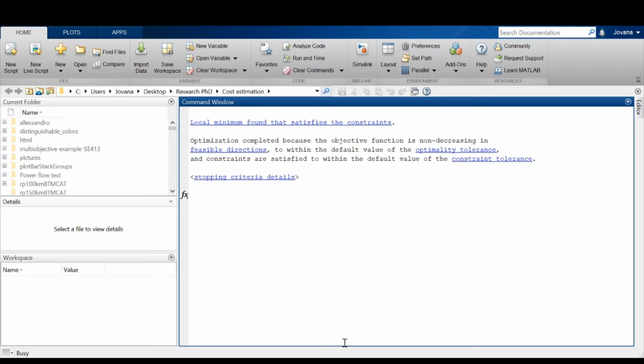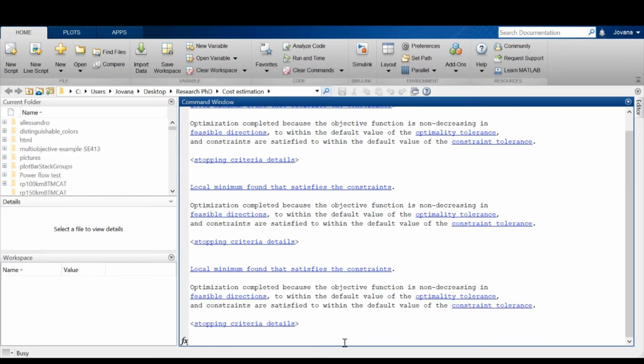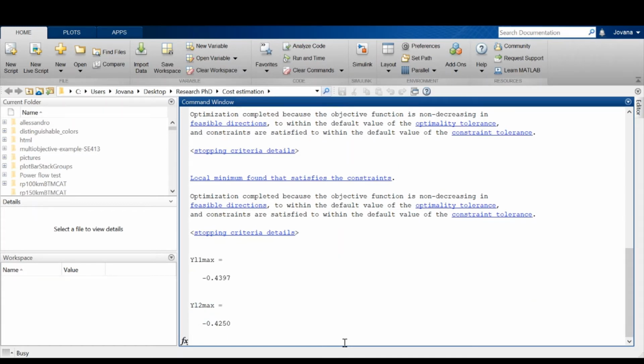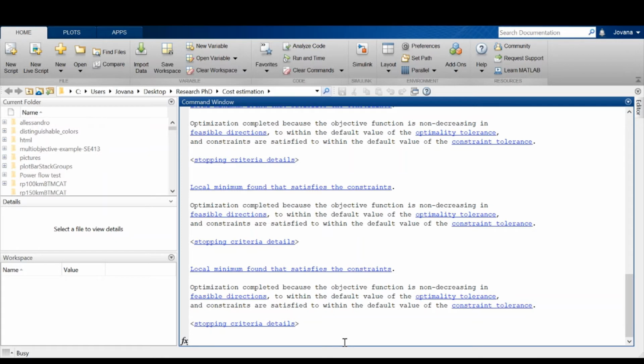While that runs, I will explain again from the methodology what the idea is. So we are testing 3 voltages, 110, 150 and 220, and all combinations of models with different reactor locations. The idea is to determine the optimal HVAC configuration, and at the end compare it to HVDC to finally decide which transmission system is more suitable for this rated power and this transmission distance.